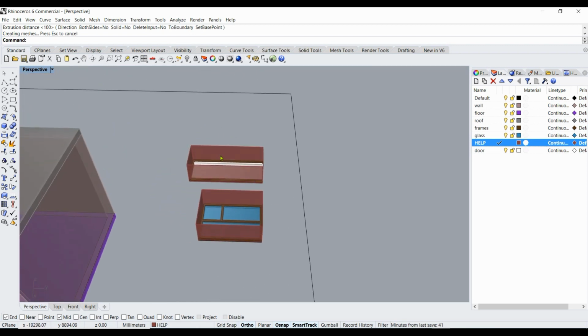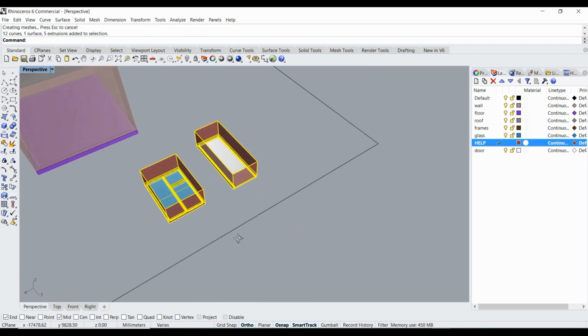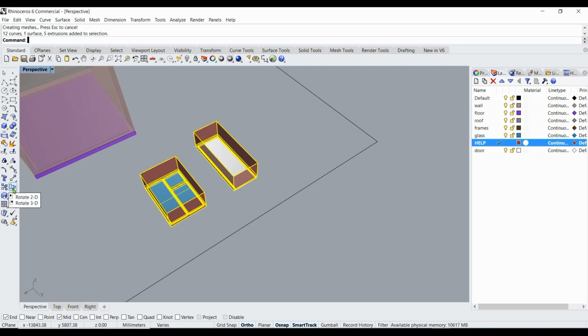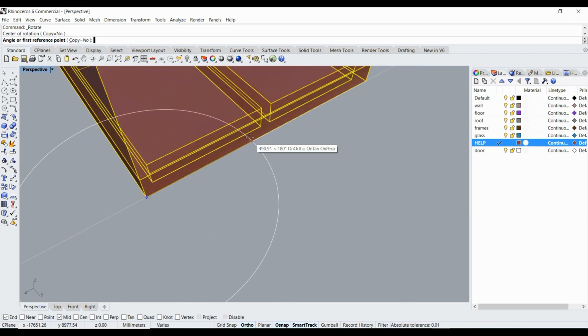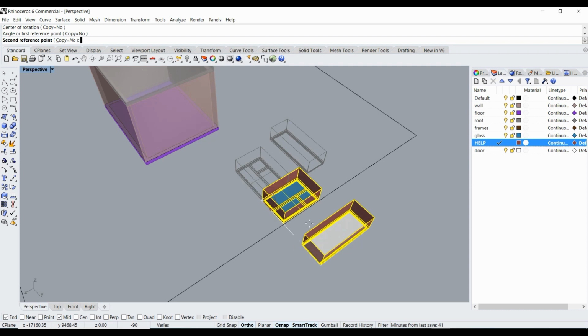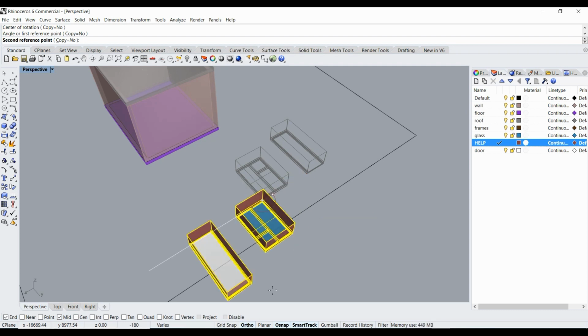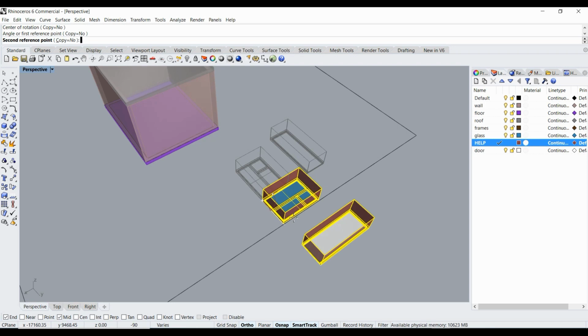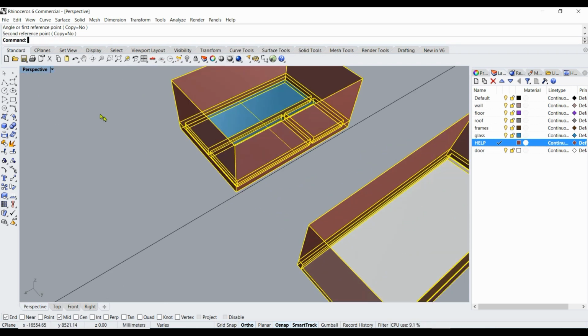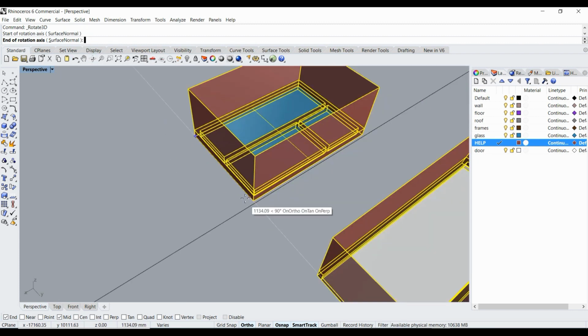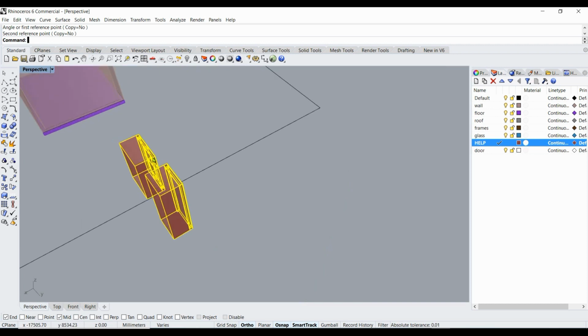And now I would like to rotate it, so I just select, and you see there are different ways to rotate. In 2D it will work in the same surface. I have the ortho on, you know. So now it's just rotate on 90 degrees. But I would like to put it vertically, so for that purpose I have to push the right button, and then it asks me for the rotation axis, so I just give it the direction, and now you see I can rotate it this way, also 90 degrees.